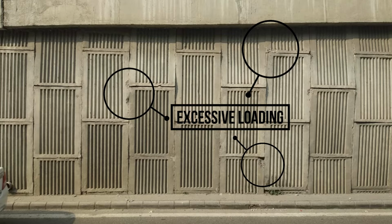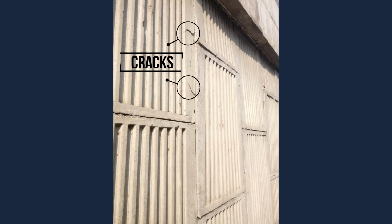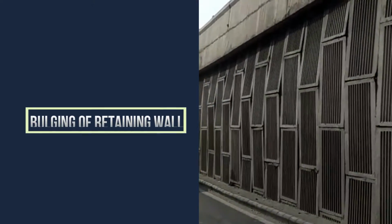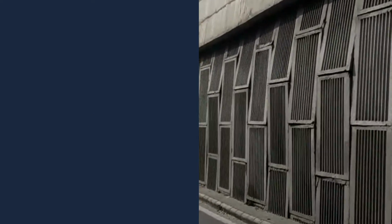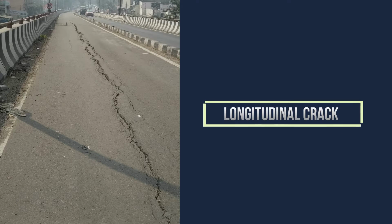In this picture, these cracks show it fails due to excessive loading. That means the majority of the load is transferred by the retaining wall. As bulging occurs, the surrounding soil loses its position and density. Then, this forms a 40 to 50 meter long longitudinal crack.